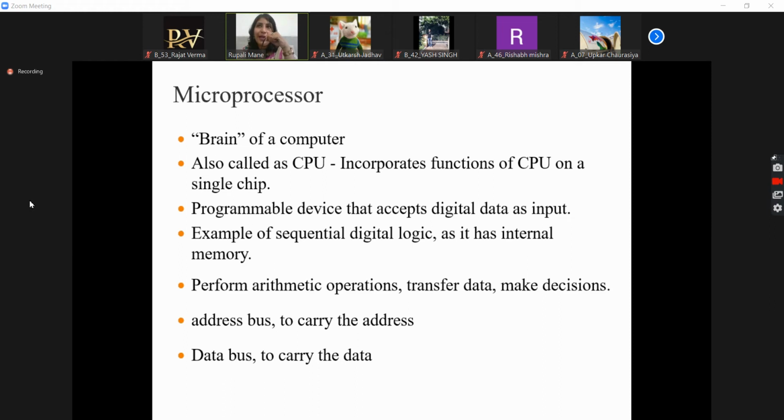Okay, if I am storing data at C000, and if in the program I am writing C001, then it will go to C001, because I have written C001 in the program. It does not understand that the data is stored at C000 and that I wrote C001 by mistake. It is not like that. It will look for C001. It will not look for C000, although the data is stored there. Whatever I am giving in the program, it will work accordingly. As we give instructions, it will work that way. Okay.